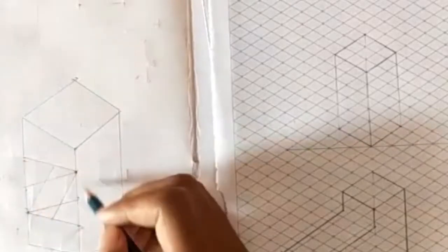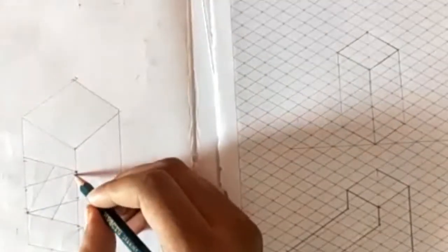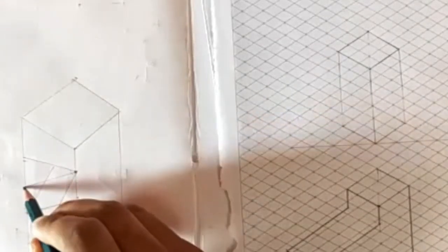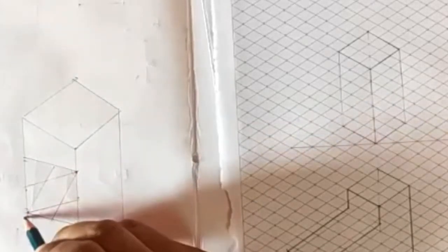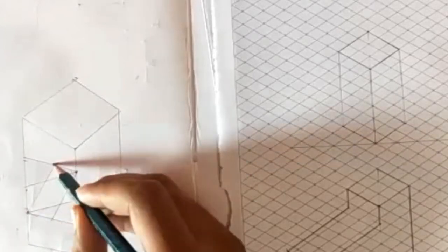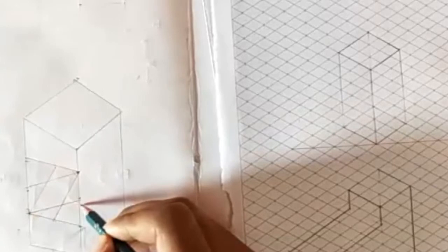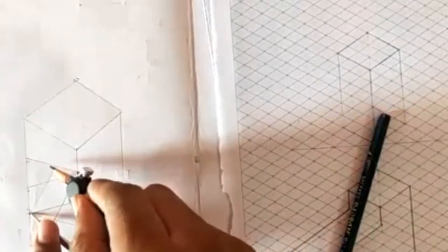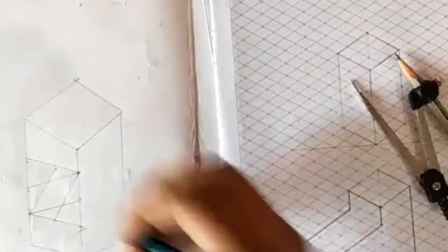You'll be drawing this box. After drawing this box, see wherever the angle is more, these 2 sides' angles are more. From this corner to the opposite midpoint, you'll be dropping a line. Again from this corner to the opposite midpoint, you'll be dropping a line. You're coming to this corner. Again from this corner to the opposite midpoint, you'll draw a line. Now, keeping this as the center and this as the radius, you'll be drawing the first curve.